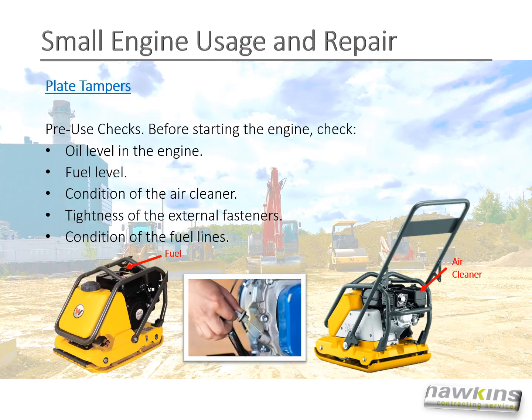Plate tampers. Pre-use checks. Before starting the engine, you should check oil level in the engine, fuel level, condition of the air cleaner, tightness of the external fasteners, and condition of the fuel lines.